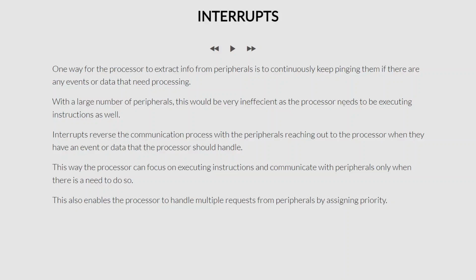And another major advantage of this approach is that now the processor can handle multiple requests from different peripherals. So let's say, for example, you have 4 different peripherals which are active in your microcontroller for various reasons. Let's say you're doing ADC, you're doing EPWM, you're doing timers, maybe even something else, right? All these are generating interrupts. They all are producing data.